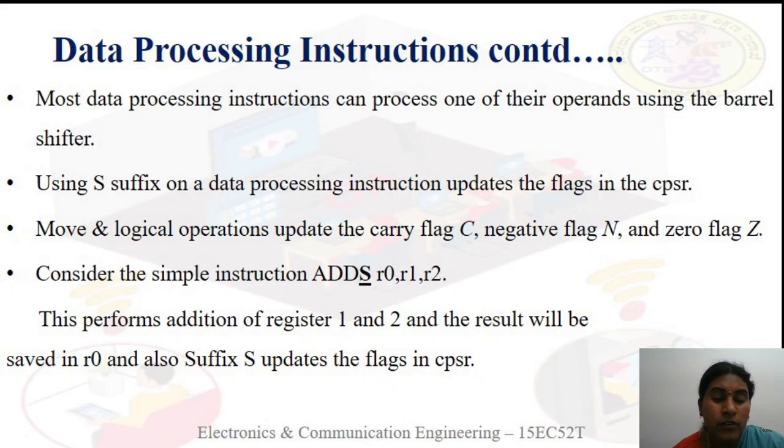ADDS R0, R1, R2 means it will perform the addition of R1 and R2 and the result will be stored in R0. And it will also update the flags. After the addition, if you got any carry, the carry flag will be set, and if the result is 0, then the zero flag will be set.